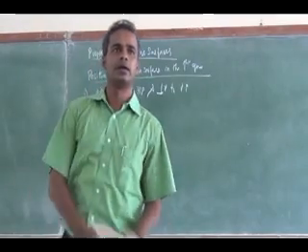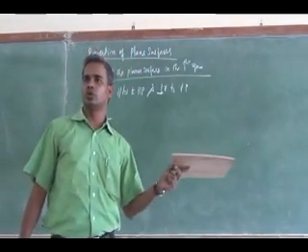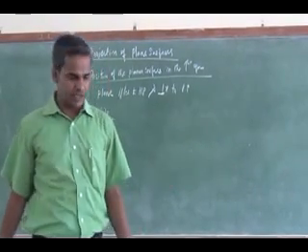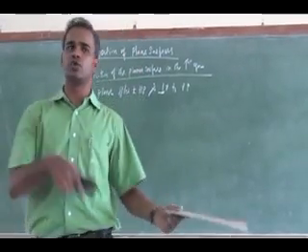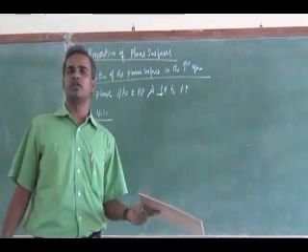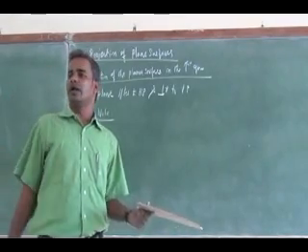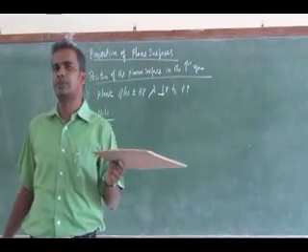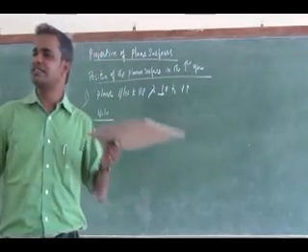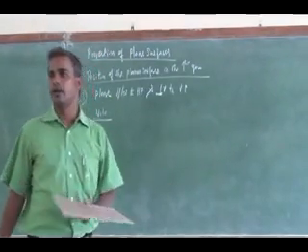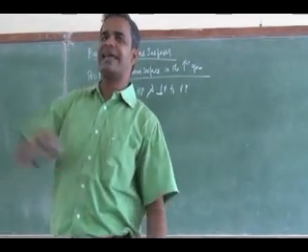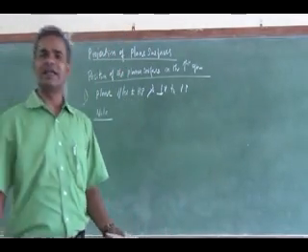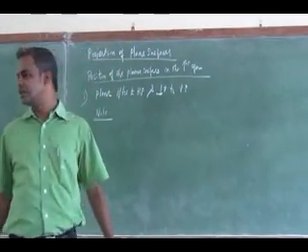So if a plane is parallel to one of the reference planes, then the true shape is obtained as a view on that plane. Is it clear? Then the second note: if a plane, meaning a planar surface, is perpendicular to a reference plane, then a straight line is obtained as a view on that reference plane.